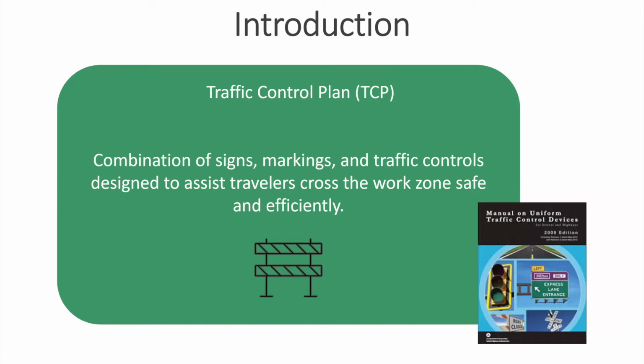Okay, so how do we protect when we're unable to close the roads to traffic? Well, we use appropriate signage, markings, and other traffic control devices. And the goal is to provide positive guidance to motorists for safe travel along the work zones so that we protect both workers and the traffic from serious injuries and fatalities.